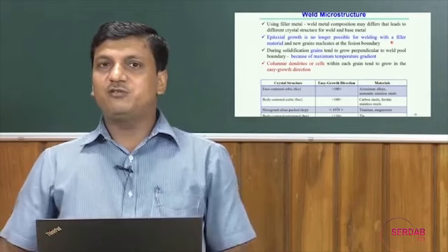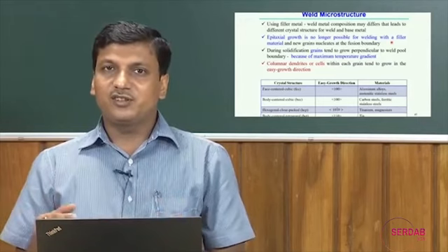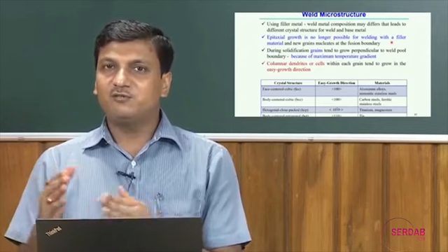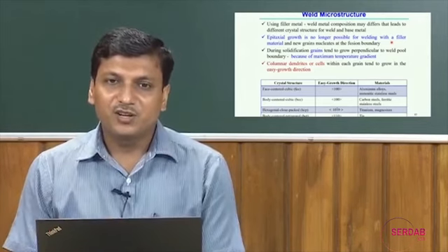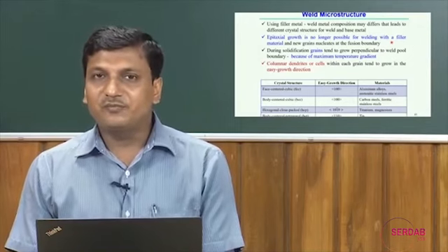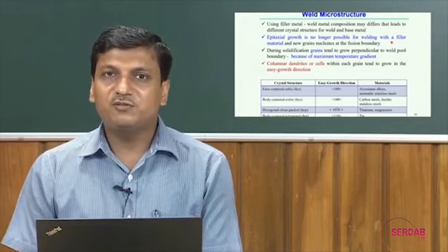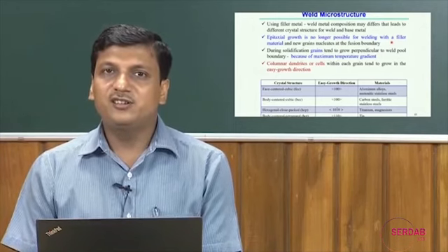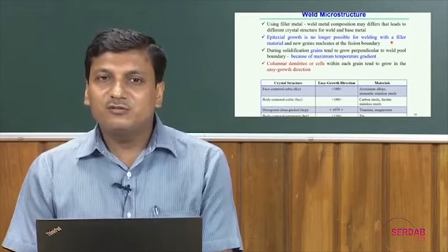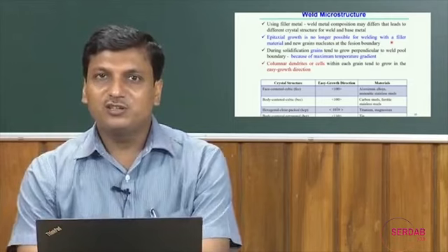That epitaxial growth mainly happens in pure metal during the welding process, along the normal to the pool boundary, because the driving force for epitaxial growth in a specific direction is probably the maximum temperature gradient along that direction. But the conclusion from here is that if we add the filler material, then epitaxial growth may not be possible in that case.